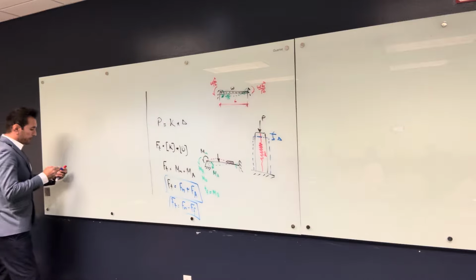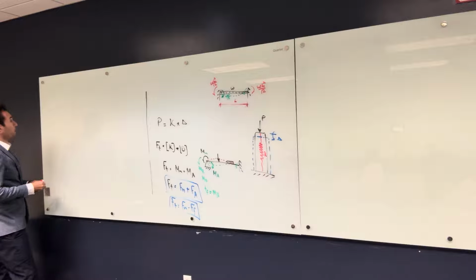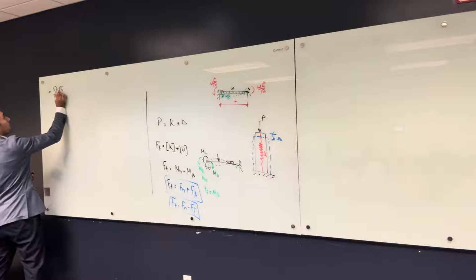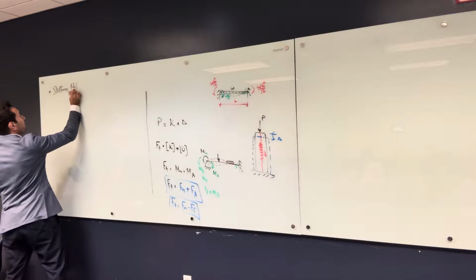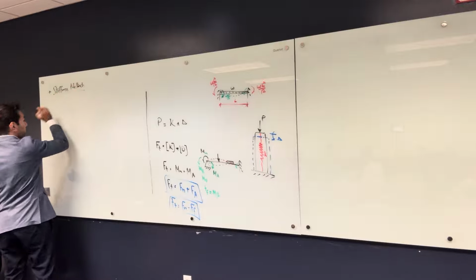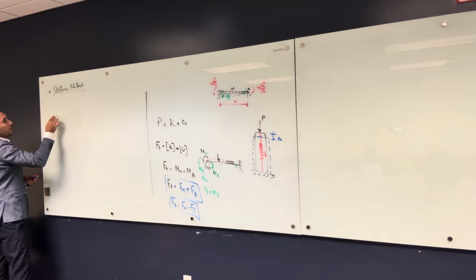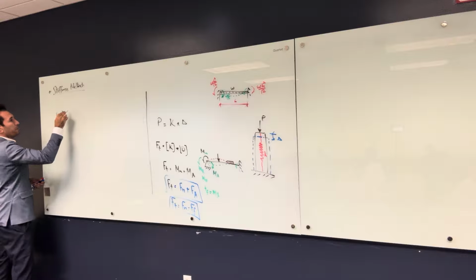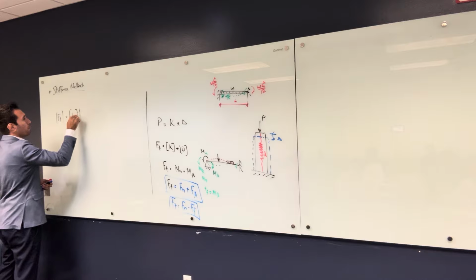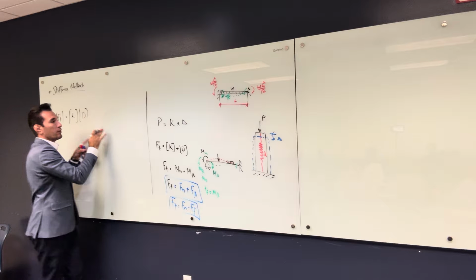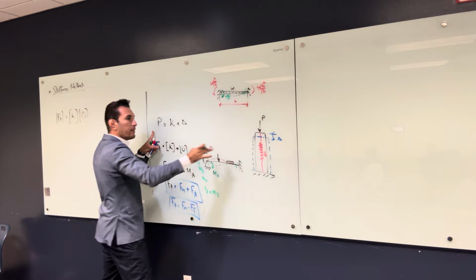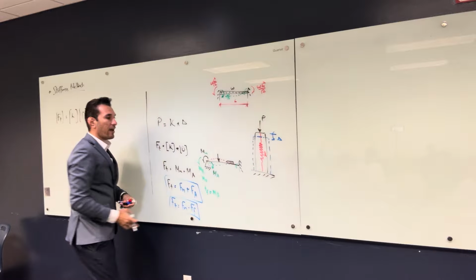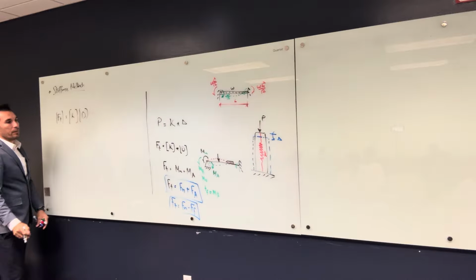So right now, stiffness method. So right now, this is the governing rule. The F total at any node is going to be equal to a stiffness matrix multiplied by a deformation matrix, which is equivalent to this one. This one was simple because the load was just direct on an axial deformation, but if I have bending deformation, it's going to be a little bit complicated.